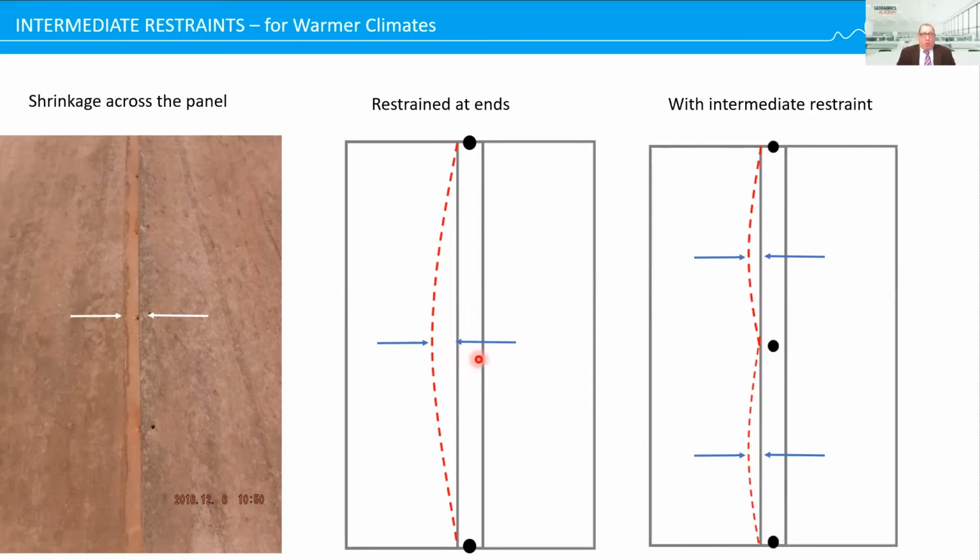And what we found, that while these shrinkages were large and outside the tolerable limit, which was about 30-35mm, by introducing intermediate restraints, the maximum shrinkage at these points is reduced by a significant factor, to amounts of around 10mm, which was within the acceptable range of the jointing systems. So this is how we detail to reduce shrinkage in joints.